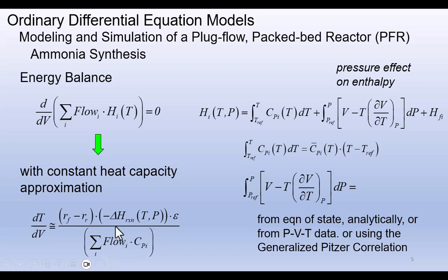So if we take an enthalpy expression in terms of a component, then we can account for its enthalpy based on changes from reference temperature and pressure by the temperature effect with heat capacity, and then the pressure effect given this particular expression with a differential with pressure.